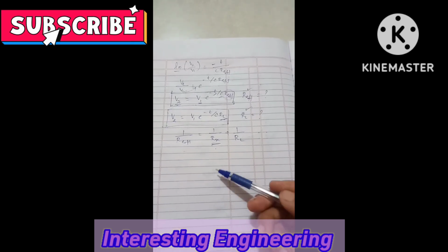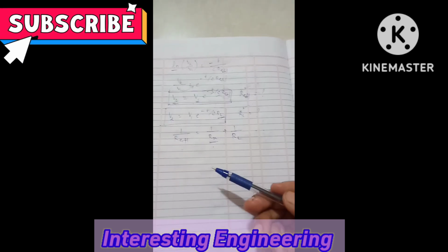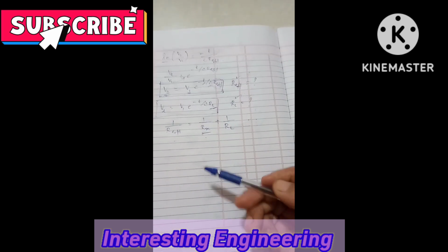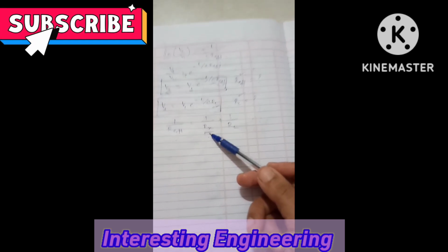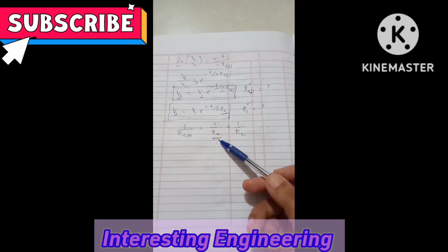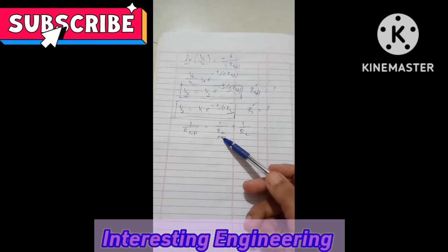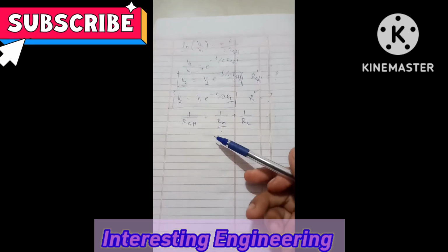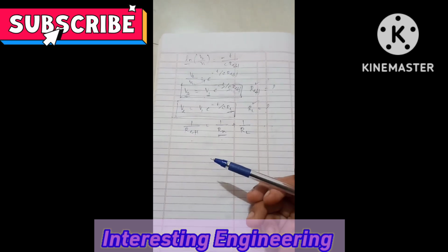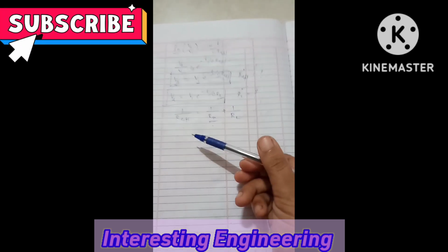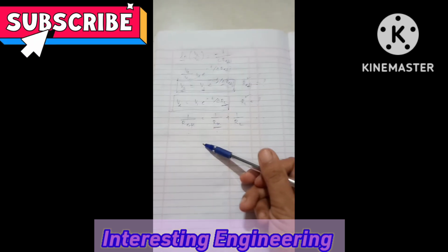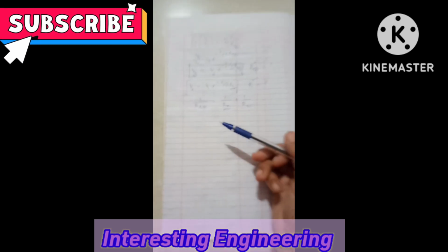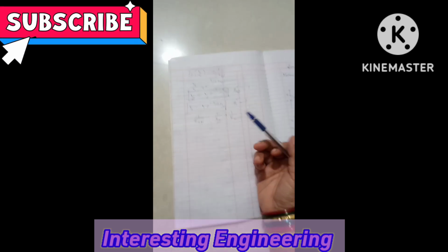So loss of charge is nothing but we are going to discharge the charge stored in the capacitor, by means of which we are going to find out the resistance value. When we make use of this method, we must know the value of capacitance and also the values of voltages at every time instance. So this is a simple and accurate method of measuring higher resistance values, and in the same way we can even apply this method for measuring the insulation resistance of cables also.